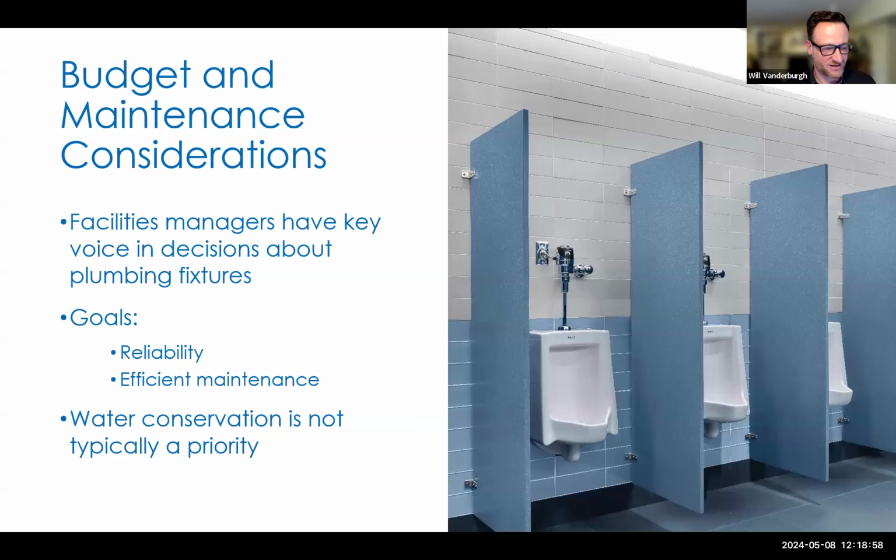But there was one more thing I was thinking. The sensor ones, they fail closed, is that correct? The sensor ones will fail closed, and they will also have a run-on protection in them as well. So if that faucet is for some reason running on for a long period of time, it'll shut itself off after 2 minutes typically. So there's a flood protection aspect there.